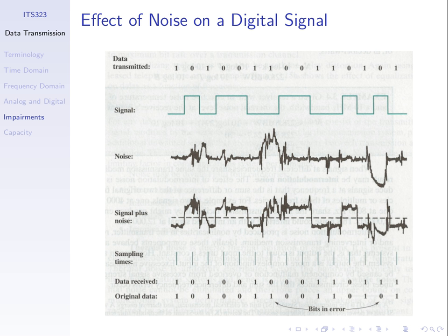When we transmit across our system, there are potentially impulses of noise, crosstalk noise, intermodulation noise, and there's always thermal noise. We can say there's a total amount of noise in our communication system. B receives the transmitted signal. It is attenuated; it gets weaker across distance. And we think of the noise as additive. That is, what B receives is the transmitted signal, attenuated, plus the noise.